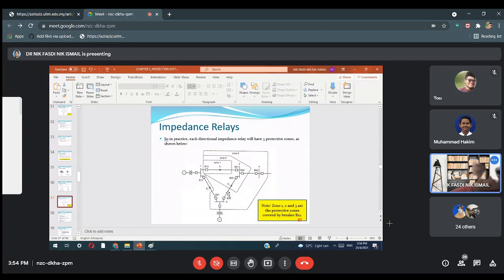So coming here, for bus 3, it will cover 100% of line 1 to 2. Okay, and then we have to choose between 2 and 4, or 2 and 3, whichever is longer. In this case, say the length of this line is longer than 2 to 4. So we choose this one. Okay. Right?